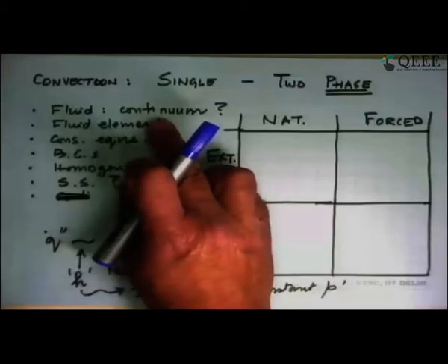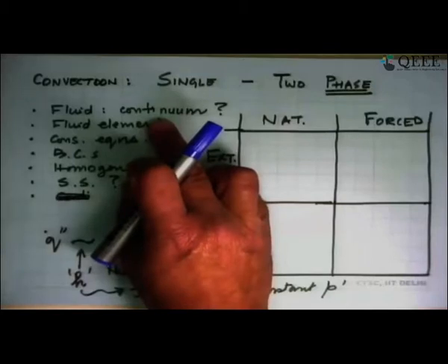Somewhere you have, in the case of boiling, a liquid. When it changes phase, it could become a vapor. So you have to deal with vapor and liquid both in the saturated state. In condensation, you have to deal with again vapor with liquid in that. So there is a problem. We do not have a homogeneous fluid which we are trying to analyze.